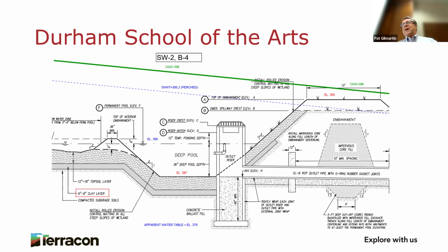The other war story I'm going to say, I don't know how many projects, contractor starts digging and they haul off the worst silts and clays. Oh, it's fat clay. I can't use that anywhere. It's unsuitable. And then it's time to build a liner for their pond because it won't hold water. What they hauled off 6 months ago would have been ideal material used for the liner. So sometimes, you know, you've got to think holistically. Maybe the bad soil in one application underneath your building might make a good liner or a berm for your stormwater pond. But don't build a stormwater pond embankment out of strippings. I've seen a couple of those and they failed.